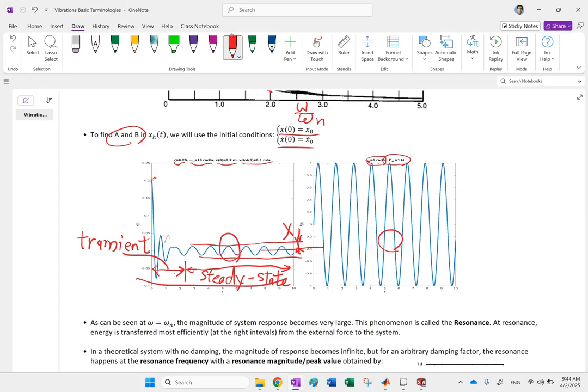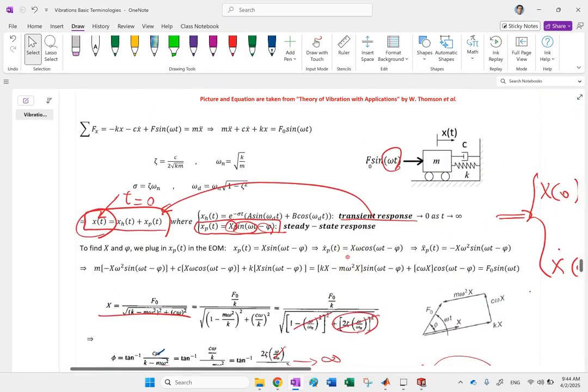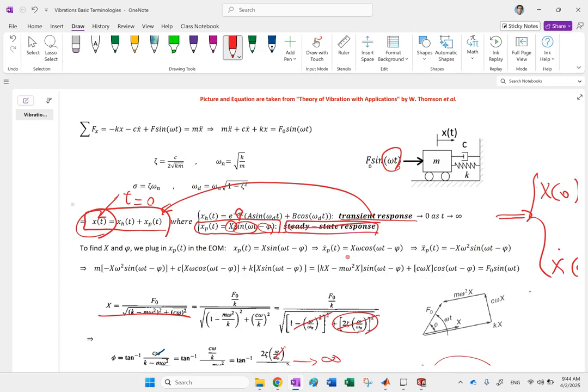So that is what you can see, a little bit of variability in this region, and then kind of steady behavior afterwards. And how long it takes, that all depends on the sigma. Okay, the bigger the magnitude of the sigma, the faster the transient response, the homogeneous part of it, goes to 0, and it becomes stable and becomes just pure steady state response.